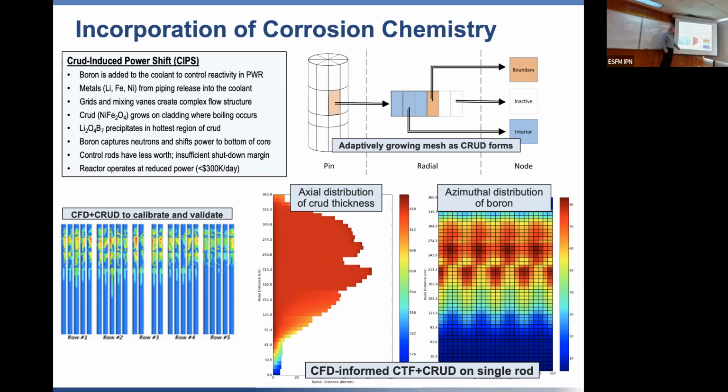If we look at where that subcooled boiling is happening, it's generally happening in the upper third of the reactor. So if boron starts getting caught in that upper third of the reactor and staying there, even though the rest of the reactor has it flowing through the water, then you wind up having more neutron absorption here, and it drops the power lower there. You assumed you had some cosine power shape axially, and now you have a big power at the bottom and lower at the top. And that matters because in a PWR, the control rods come in from the top.